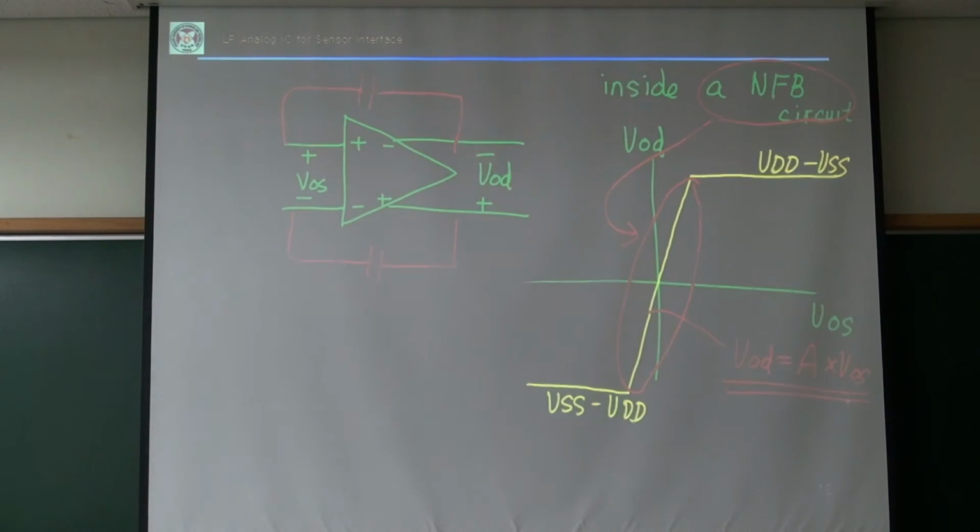Okay, so your question is, if I use an output buffer, something like it may be two stage. This is a unity gain buffer in this op-amp. Then yeah, I can just use a resistor because my output resistance is pretty small, right? But this can generate some additional gain, an additional stage, right? We don't like this unity gain buffer. Then yeah, I need a capacitor, this capacitor or switched capacitor.